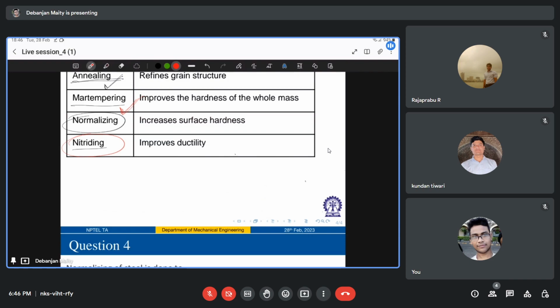A thick case of high hardness and wear resistance is produced in carbon alloy steel. What you do is immerse your specimen in a salt bath containing NaCN, sodium cyanide, which you heat up to some temperature range, let's say 820 to 860 degrees C. This is usually followed by water quenching.